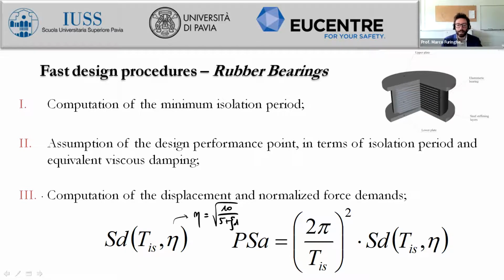So that is a reduction factor for the elastic spectrum, which provides the scaling effect of the response spectrum with respect to increasing values of damping ratios.